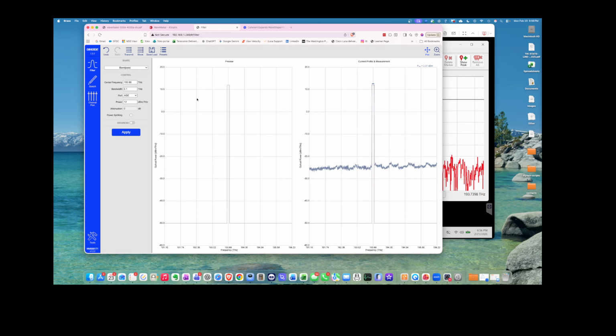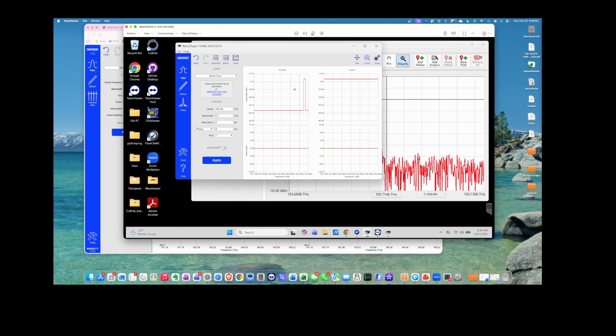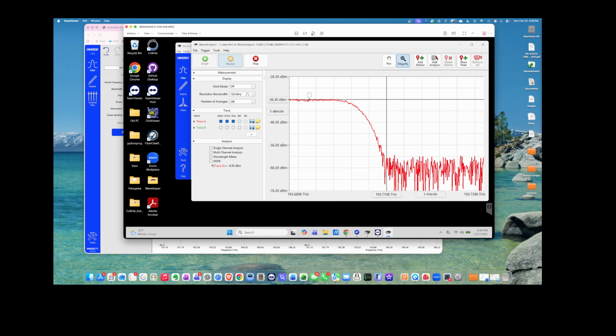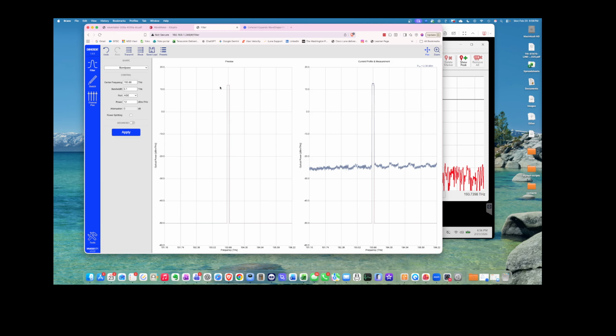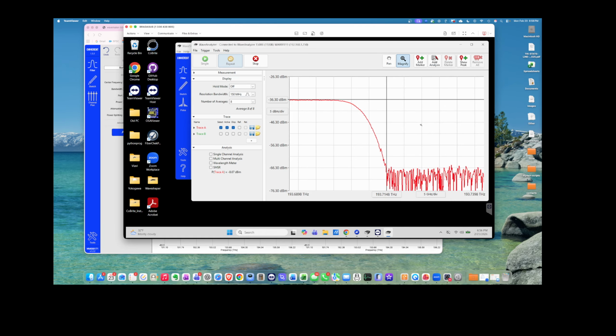And then I have this going into a Waveshaper Sharp, and the output of the Waveshaper Sharp going into a wave analyzer, spectrum analyzer. With the Waveshaper Sharp, I'm just transmitting. I'm sending everything through at transmit level. So the Waveshaper Sharp is essentially out of the circuit here. What I'm looking at here is the filter shape, and I'm looking at the falling edge of this filter right here. I'm putting a few averages on just to clean up the noise a bit.